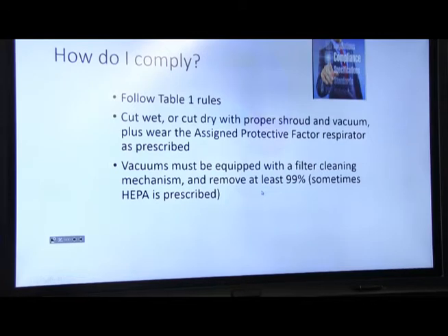So when we do follow the Table 1 rules, and I will make sure that every job site has a copy of this to put in their safety manual. It's really rather simple. For all of these tasks where you're going to be cutting or grinding and disturbing silica, creating silica dust, we're going to have to either cut wet, which has always been a pretty standard practice, especially if you're core drilling or saw cutting.